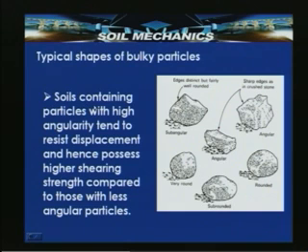Soils containing particles with high angularity tend to resist displacement and hence possess higher shearing strength compared to those with less angular particles. As we said, the shape of the grain is very important for coarse grained particles.